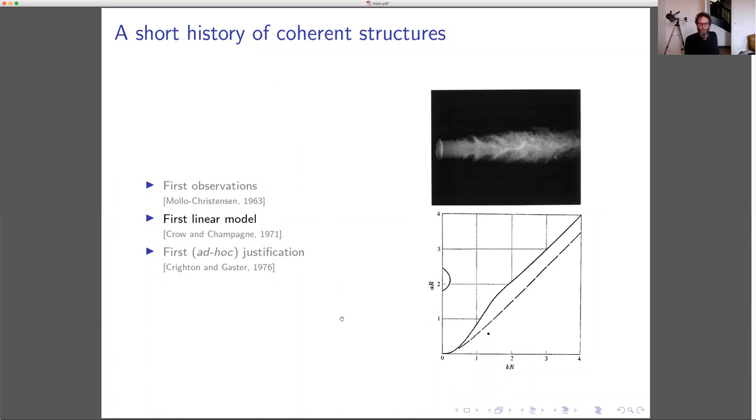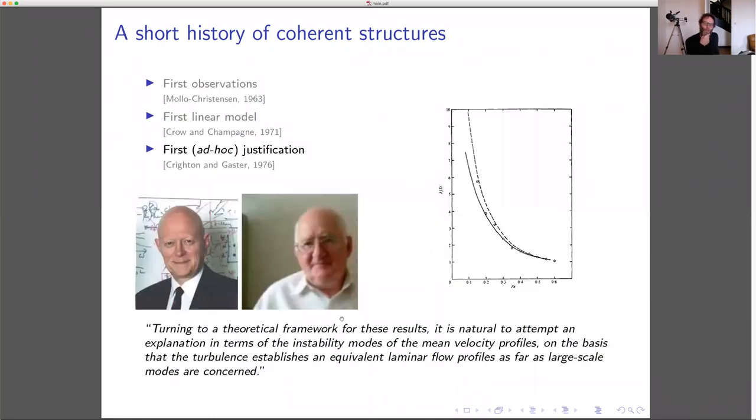that we see in turbulent jets. And I've cited Crighton and Gaster here. Basically what they did was they extended the local analysis to a weakly non-parallel scenario using a multiple scales approach. So this is a WKB type approach. The data points on this plot come from Crow and Champagne. So now we're looking at wavelength of the organized structures as a function of frequency. One of these lines is the locally parallel analysis. The other is the weakly non-parallel analysis. And you can see again that there's a nice match between this simplified theory and the data from the turbulent